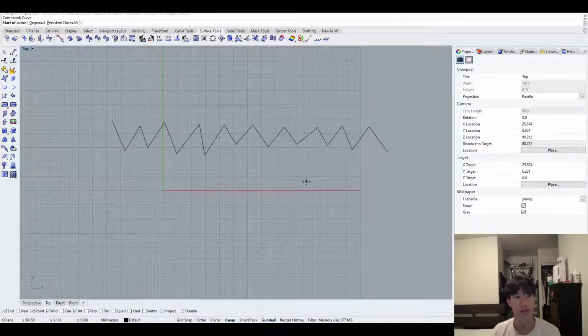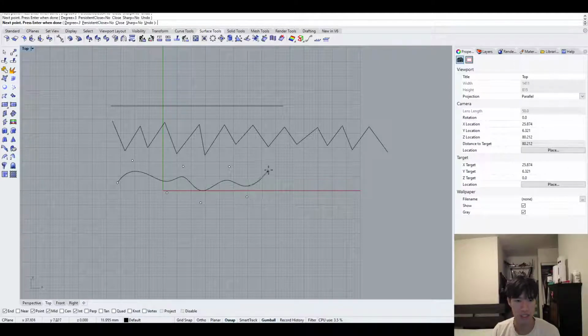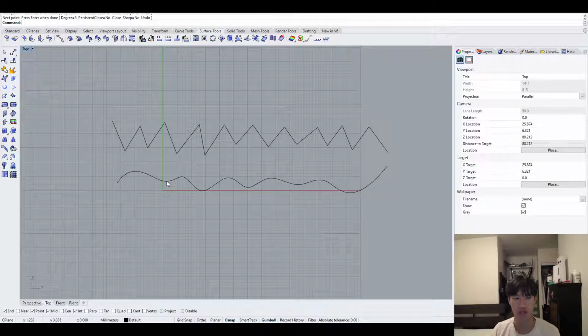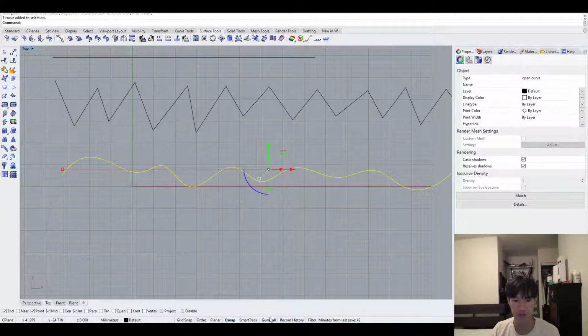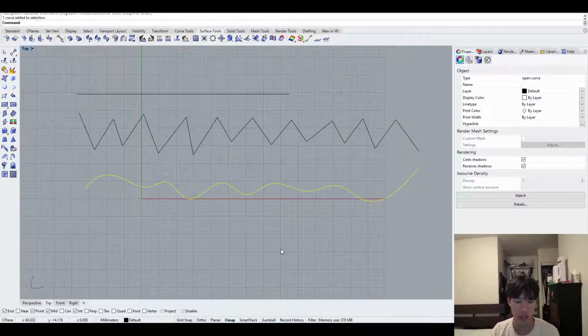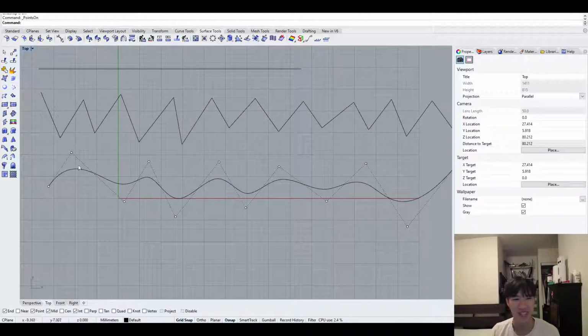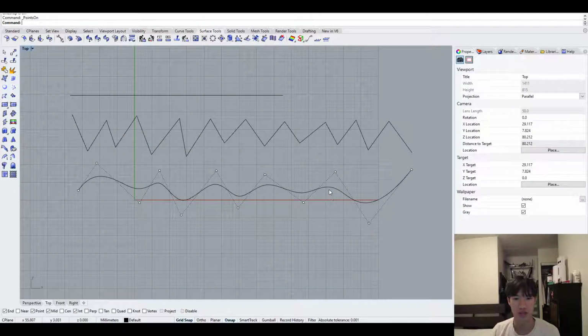Curve, you can use this to draw curves. You basically place control points, and Rhino builds a NURBS curve based on these control points. And if you click on a curve and you press F10, wait, no, sorry, I pressed F9, F10, right? So if you press F10, it turns on the control points, so you can see the points.